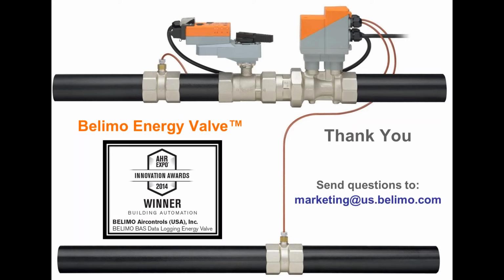In other words, if you have a 16-degree chiller and you're generating 20 degrees of delta T and that 20 degrees is showing itself to your chiller, you're going to get a reduced performance the higher that number gets. Now, I'm not a chiller expert, so I can't really tell you where the tipping point is, but typically when I work with customers, we're trying to match the plant.